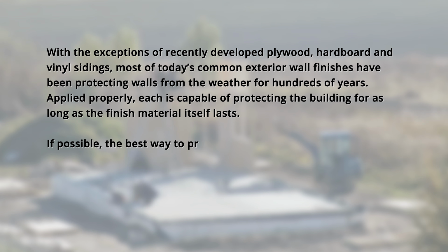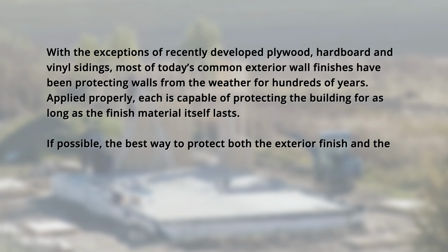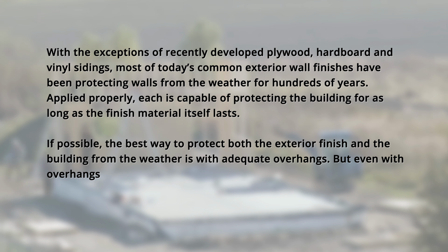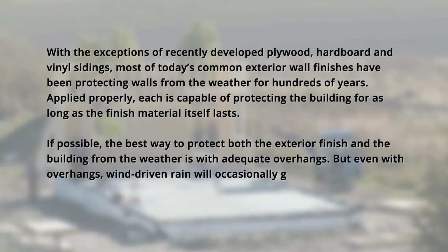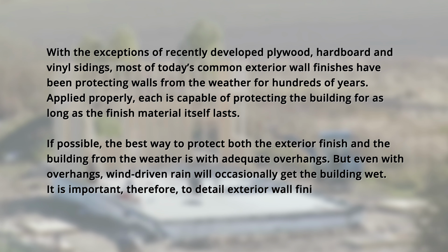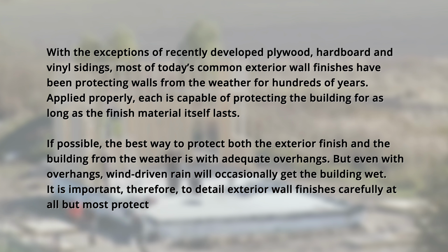If possible, the best way to protect both the exterior finish and the building from the weather is with adequate overhangs. But even with overhangs, wind-driven rain will occasionally get the building wet. It is important, therefore, to detail exterior wall finishes carefully at all but most protected locations.